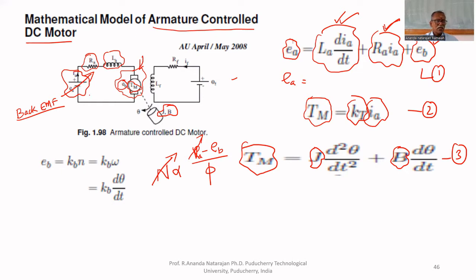That is one way. Another way is to change the flux. The armature needs a flux, and the flux is generated by the field coil. If you adjust the field voltage to reduce the flux, you can increase the speed. If you increase the flux, there will be a decrease in speed. So the opposite way is also possible.